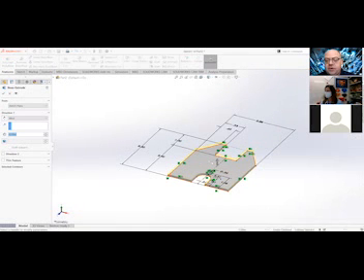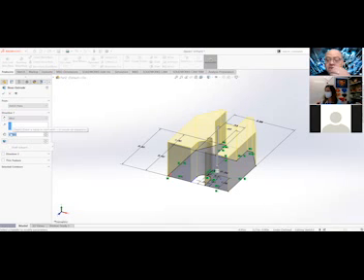As soon as you do that, it's now got a 3D preview. There's an arrow you can drag to see about proportioning. Over on the left side is where you put the actual value in. So how thick does this need to be? Well, if we looked up your drawings, it needs to be 1 inch thick.